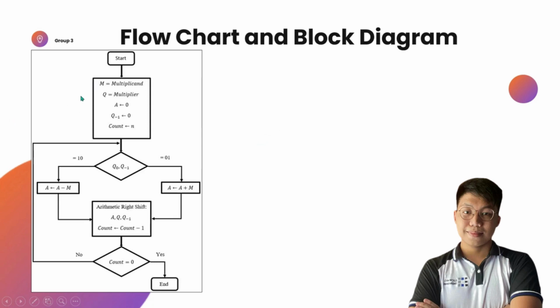I will be discussing the flowchart and block diagram. This figure shows the flowchart for implementing the Booth multiplier. Initially, we have multiplicand M, multiplier Q, our product A, and our 1-bit register Q1. A conditional statement is applied for the values of Q0 and Q1. Q0 is the least significant bit of the multiplier, and Q1 is the assigned bit of the 1-bit register. For the case that the values of Q0 and Q1 are 1 and 0 respectively, the multiplicand is subtracted from the partial product. On the other hand, for 0, 1 values, the multiplicand is added to the partial product.